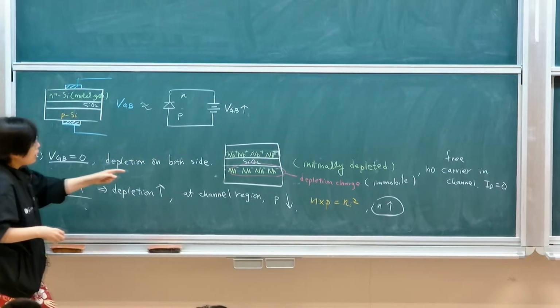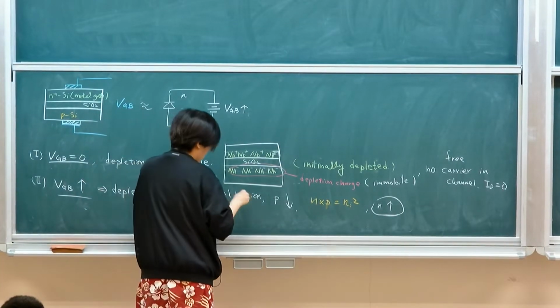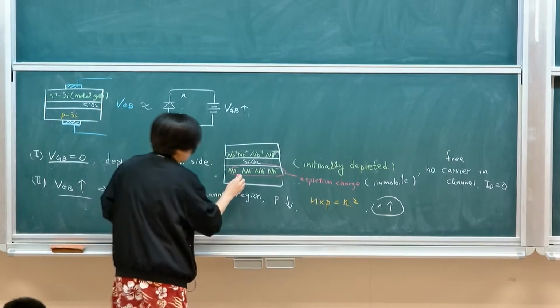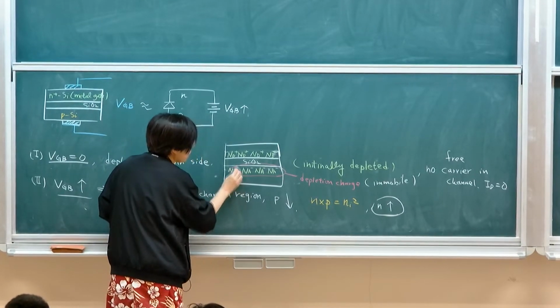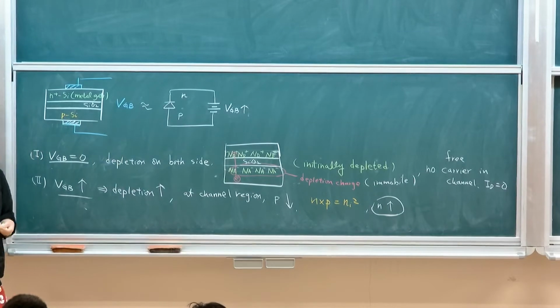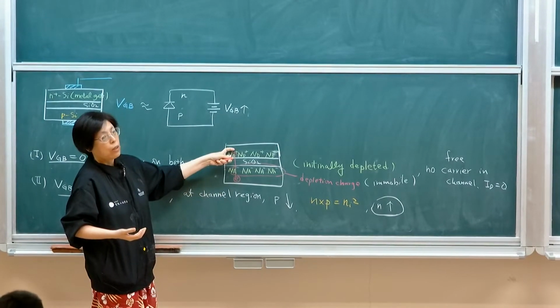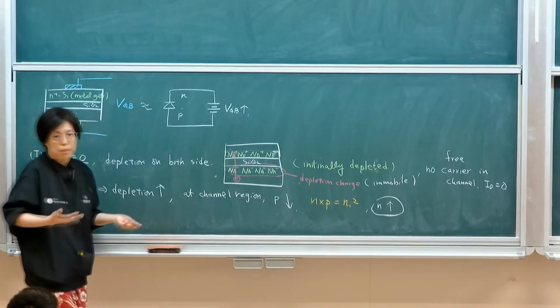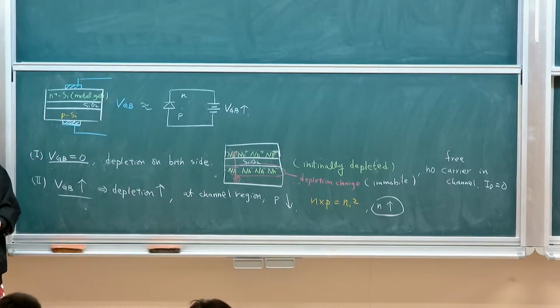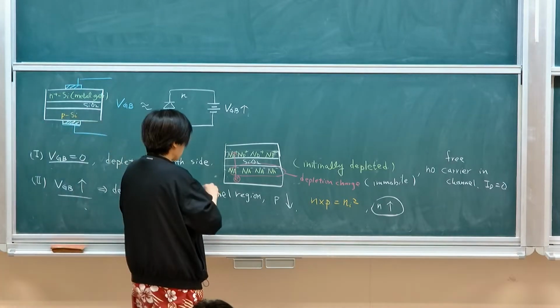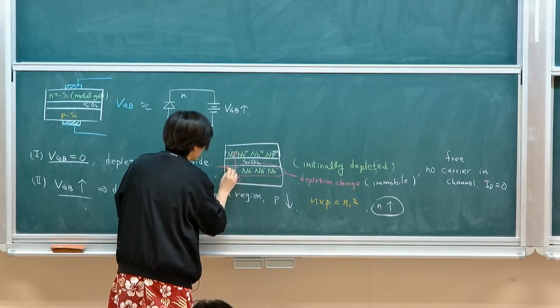But now if there's electrons being generated here, if you think about it, some electrons being generated try to move across to the other side because the electric field tries to pull them over, but they will then hit the glass. So the way to think about this is that I have generation of electrons, and the electrons will be pulled by the electric field to go to the gate. But they cannot go to the gate because they're being blocked by the insulating region. Therefore, you will see electrons accumulated here.